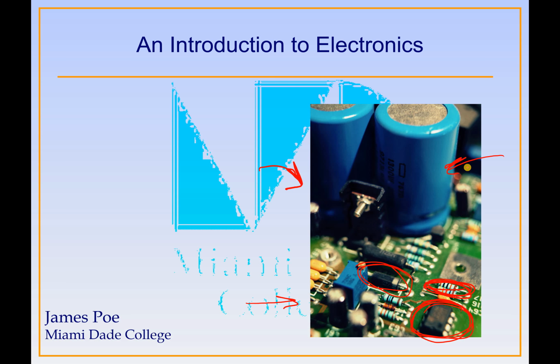These big boys up here are called cans, because it kind of looks like a can. Actually, they are capacitors. You're going to learn about them next semester in AC. By the way, be careful. If you're ever going through a junkyard or dumpster diving, don't ask, maybe sometimes I do that, you need to be careful of these things. They can explode. They can hold electrical charge months, even years, theoretically forever, after they've been disconnected from a circuit. People used to get really hurt. When they would go look for big old TVs, they used to have those big capacitors in there and they would shock or kill themselves by trying to grab it. So do not touch. Moving on.